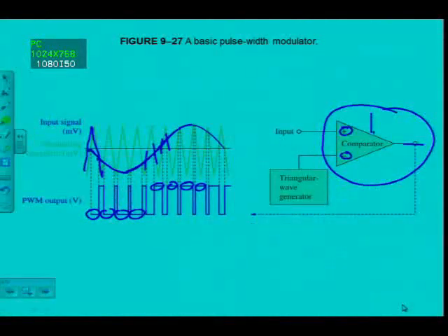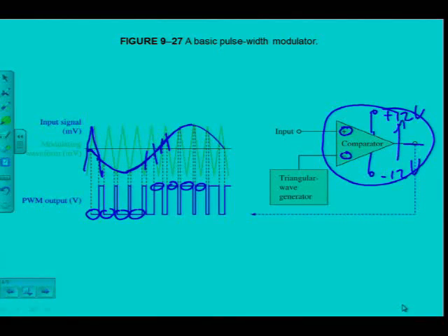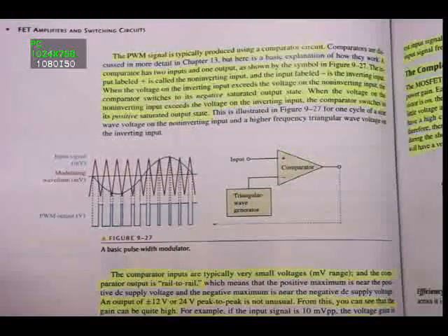All right. So the voltage is applied on this circuit here. I think in the example there as well, there's the voltages applied to this device. Say it's plus 12 volts, minus 12 volts. Of course, the difference there, or the voltage range there, is 24. Now, minus 12 and plus 12, the range is 24. So the comparator will switch the voltages to close between the 24. Now, it cannot go exactly up to 12 volts, just below 12 volts. All right. So that is what rail to rail means.